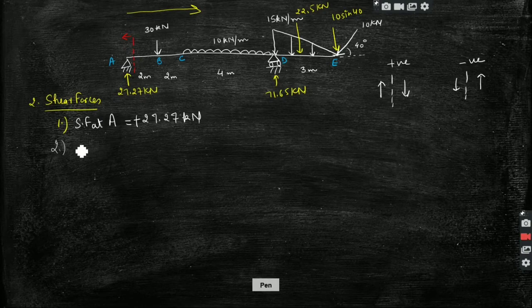We will move to point B. So I will calculate shear force at B. And just to make a habit, always take a section on both sides of a point in the span of the beam. Like I am taking point B, and I am taking one section just at the left and then I will take one just at the right. Its significance we will come to know later on while solving different questions. So it is easier to visualize our beam like this.